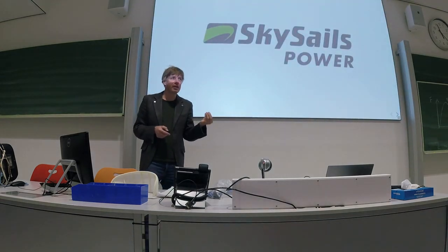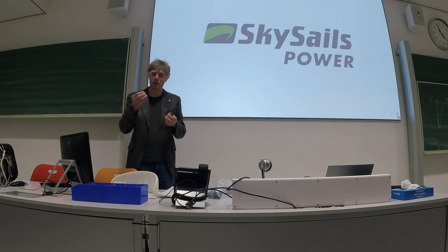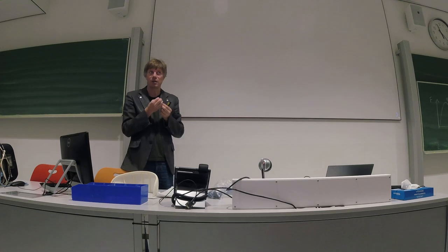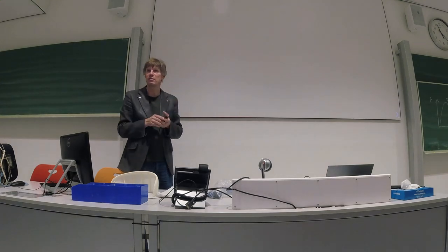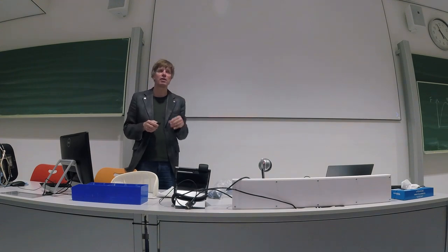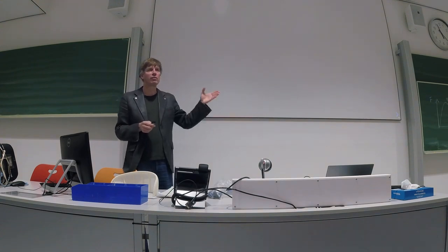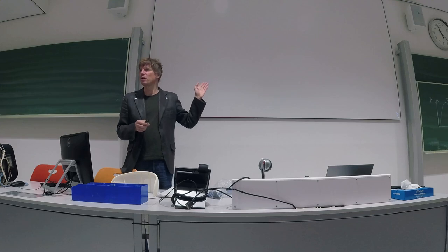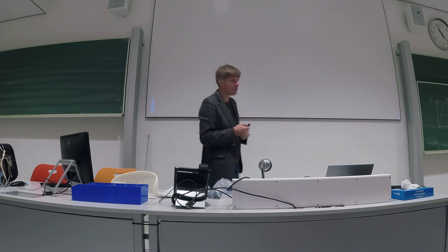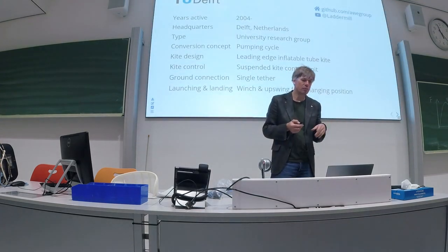That is required so that you can decouple and couple back the kite to this mast. We are using this fifth line also with kite power, and I will show you later, but not for mast-based launching, but as a safety mechanism when the main tether breaks, which it shouldn't.